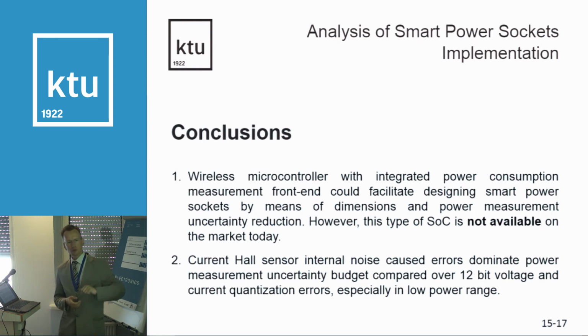Then current Hall sensor internal noise caused errors and dominated the power measurement uncertainty budget when we have over 12-bit voltage and current quantization errors, especially in the low power range.